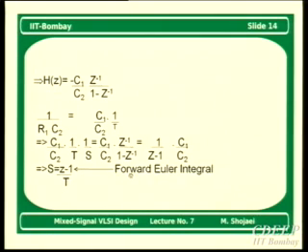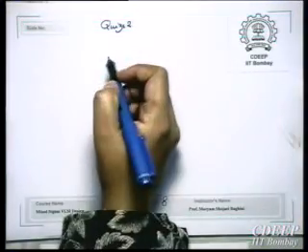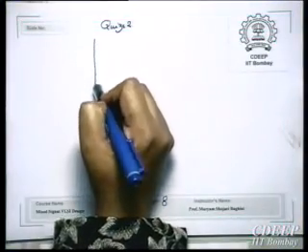Of course, because forward Euler, as we discussed last time, may lead to instability, it is better to use a scheme which emulates backward Euler. So now we will continue in this lecture with backward Euler implementation and also bilinear definition and implementation, and example circuits. Okay, so we want to design a bandpass filter.